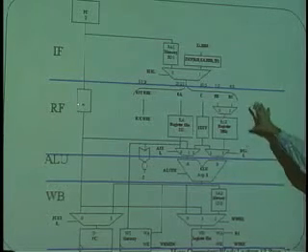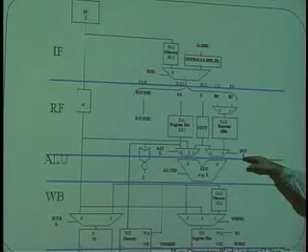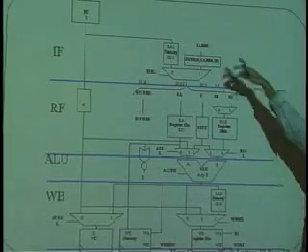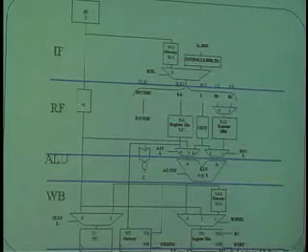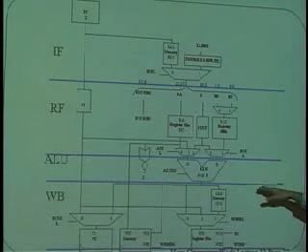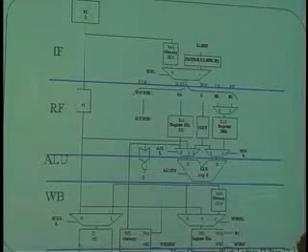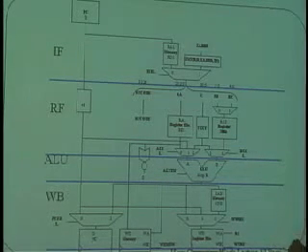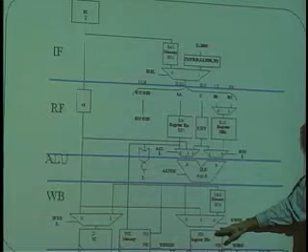And then I've gone and I've kind of chunked the rest of the machine accordingly so that this is a stage, the ALU is a stage, this is a stage here where we read the register file, and this is another stage here where we look up, given the PC, what the opcode is that we want and feed it in here. And we should be able to clock this machine at a period which is equal to what? The maximum delay in any one of the stages. And all the clocks are going to go off at the same time. Kabang, everything shifts down by 1. Kabang, everything shifts down by 1. But any given instruction is going to take 1, 2, 3, 4 clock cycles to get done.